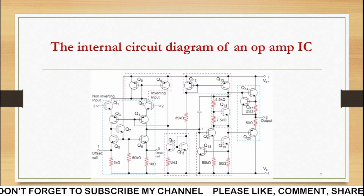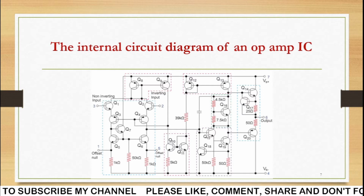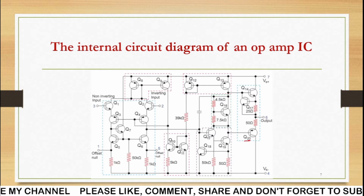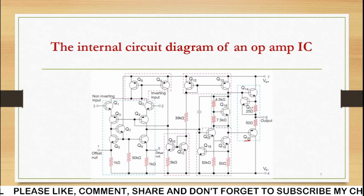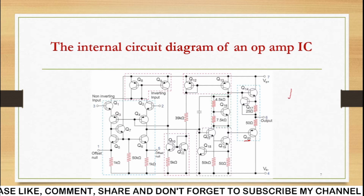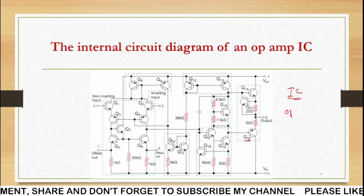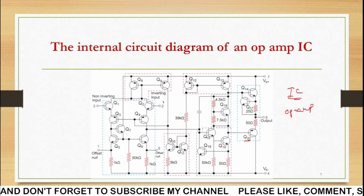So this is the internal circuit diagram of an operational amplifier, and you should know what it looks like. This is the 741 internal circuit diagram of the op-amp. Pin number 2 is the inverting input terminal and pin number 3 is the non-inverting input terminal.